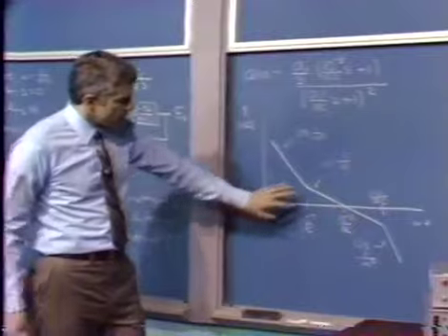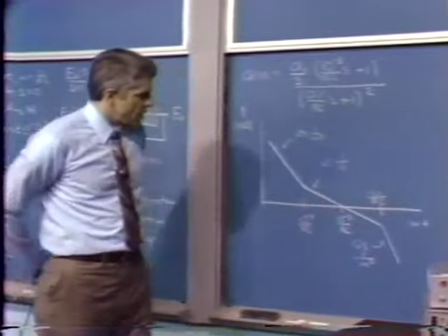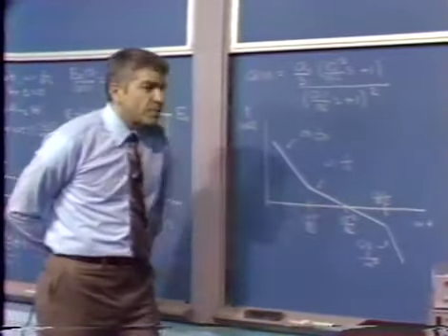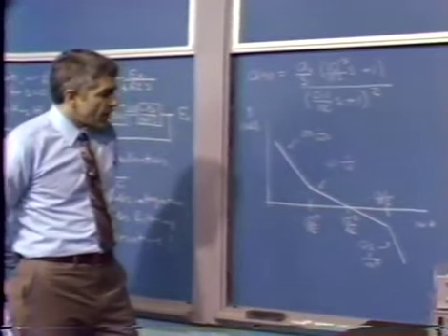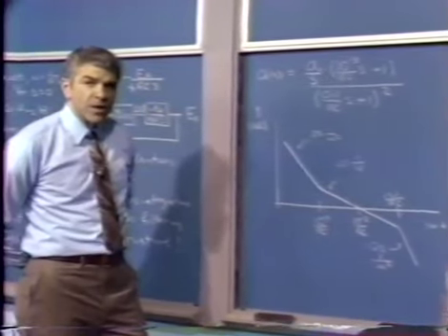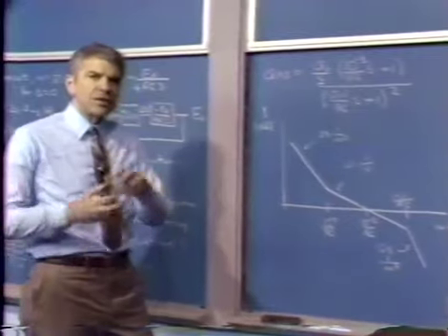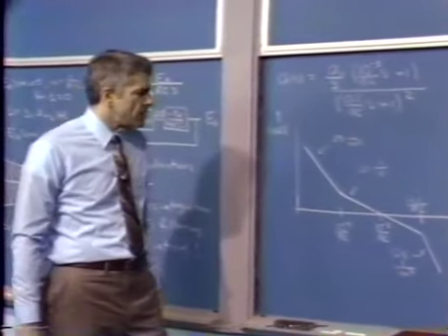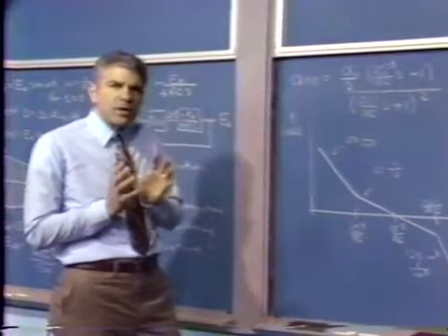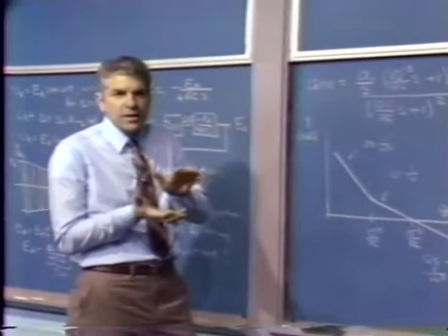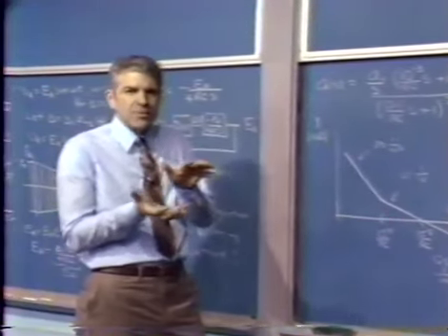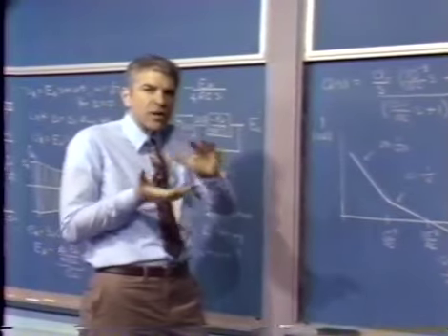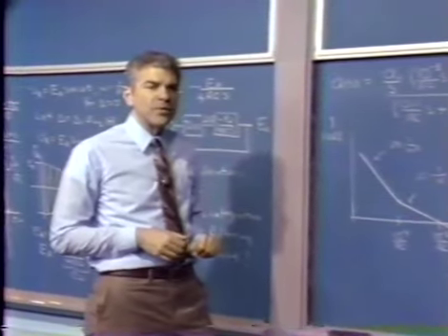Let's focus a little bit again on this relationship, the fact that we'd like to cross over at a frequency small compared to the oscillating frequency so that we don't get an interaction, a sampling kind of a thing. The only converse to that, normally, is that our amplitude control loop only has to make up for aging and temperature changes and that sort of thing. And so a very slow amplitude loop is perfectly fine.